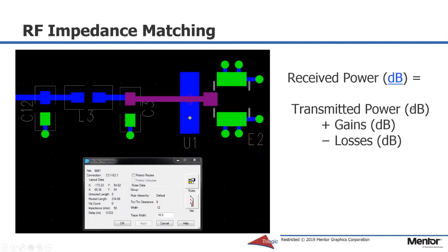So as I previously mentioned, this is a very common place where designers unintentionally lose signal because the output and the input of the radio are connected to this. So although chip down and modular radio solutions are ubiquitous today, the necessity of an electrical and geometric link between the radio and antenna exists in all wireless IoT devices.